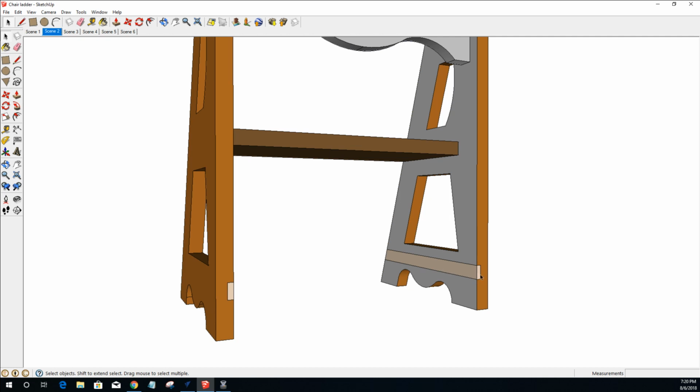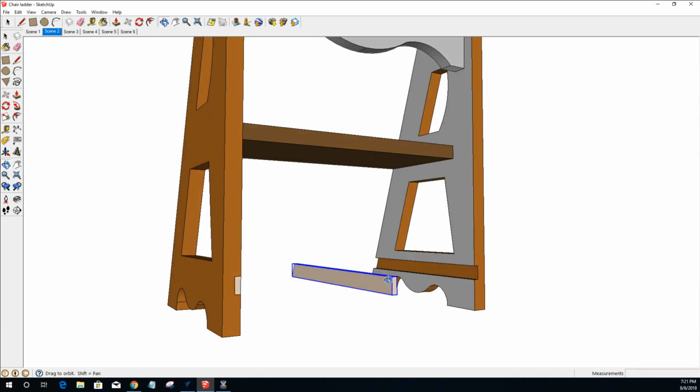They're 1/4 inch deep by 3/4 inch splines basically, and they're glued in so that this short grain area here, for this lower part, is reinforced, because if this chair were to break or fracture, it's going to be around this area. So these splines are there to reinforce that area.